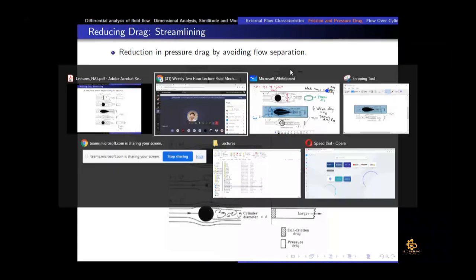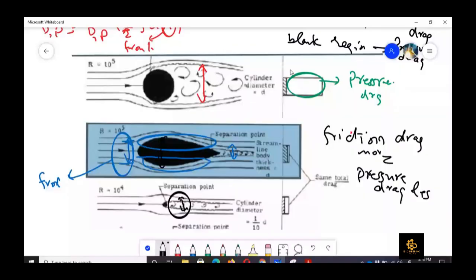Yes, Tabriz, very excellent point. Because if I write the formula for the drag force here, that was CD into half rho U square into area, right? So area is kind of same. If you see the figures, the frontal area here is the same as the diameter of this. Rho would be the same. CD value would be of kind of the same magnitude. The only difference, which is very applicable and quite dominant, is the U scale, right?